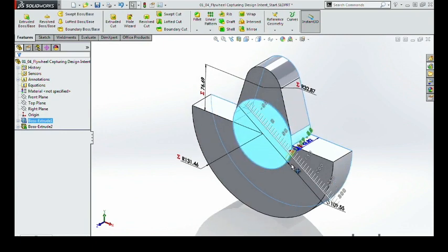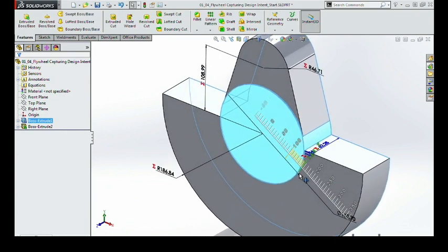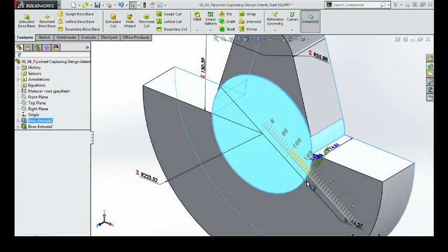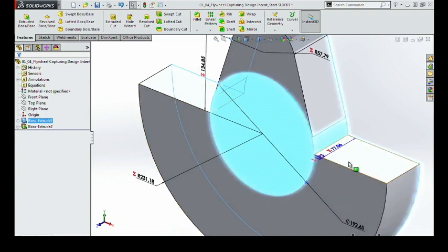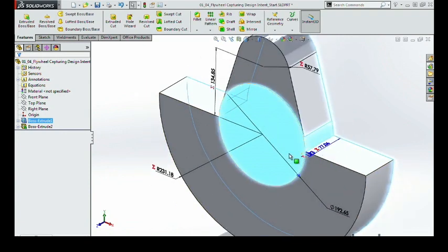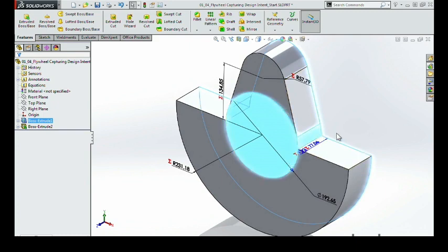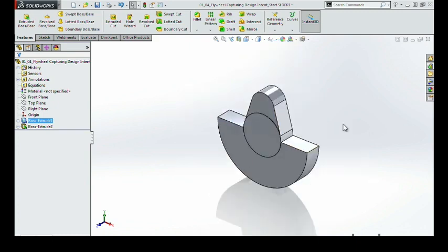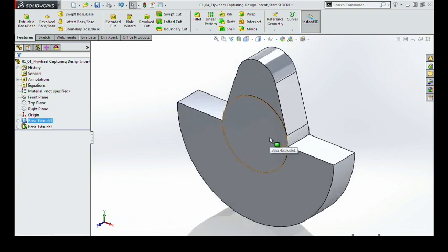As we now drag the blue orb, we can see that the entire model scales as it should, including the extrusion depths, and our design intent is now fully captured for this stage of our design. With some upfront consideration and planning, you can build solid models in this way. Use Instant 3D to constantly test your design as you build and constrain.